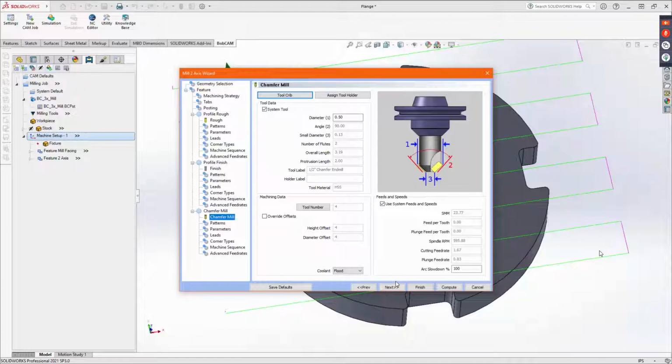Now chamfering, something that I always like to bring up is that you don't need to go crazy defining your tools here. When you're setting up a chamfer mill, just define the diameter. We're going to do the rest of it for you a little bit later on. So even if your tool is a different diameter, different angle, different small diameter, don't worry about it. It's your sharp tool, flat tool, none of that really matters at this point. So let's just say it's a 1/4 inch diameter.